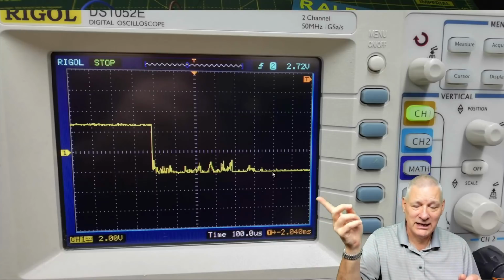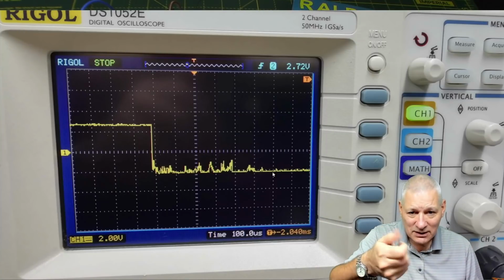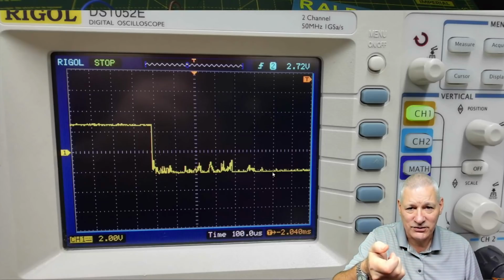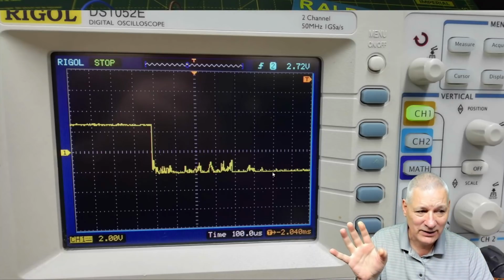In fact, my telly, the remote control works well enough 99% of the time, but sometimes you press a button for the change of the channel and you get the number 4 come up twice, for example. You think, well, I only pressed it once, why has it gone 4-4? And then, of course, you're stuck. You have to put another number in to make it go around the loop again. I know. So switch bounce is one of those things you do want to get rid of.